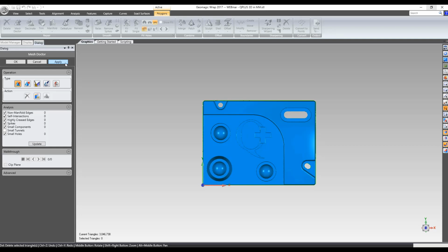In today's webinar, we will be discussing the 3 different reverse engineering techniques used to obtain a solid model from scan data. This solid model can later be used in a downstream CAD package. We will be using 3 different Geomagic softwares to achieve this. In Geomagic's Wrap, we will be creating an auto surface solid model. In Geomagic for SOLIDWORKS, which is a SOLIDWORKS plugin, we will be doing hybrid modeling. Hybrid models use auto surface modeling and parametric modeling together.